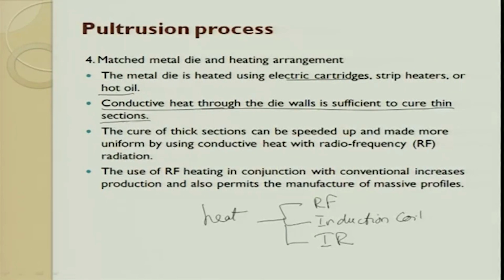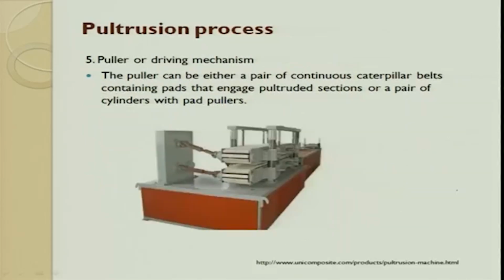the curing happens. Interestingly, we are trying to work on thin sections also. In thin sections, if the heat is not properly applied, it always tries to warp. That is one thing. Curing of thick sections also needs to be done in a very quick fashion, so we go for radio frequency or infrared.